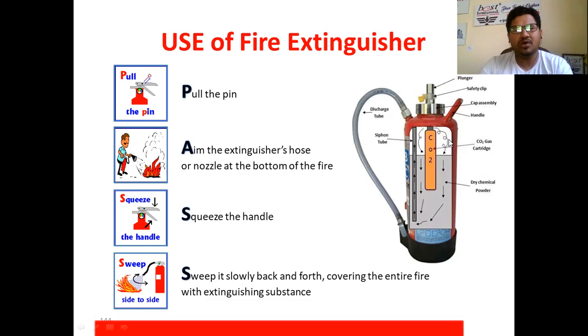But if it is in the red zone, that means either the liquid or powder inside is finished. Especially, we use plenty of multi-purpose fire extinguishers now, and mostly they have a gauge. So make sure you see the gauge before you even use it. And yes, the distance between your standing position and the fire must be the safest one. Don't be so close.